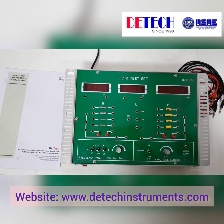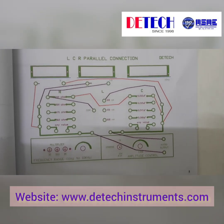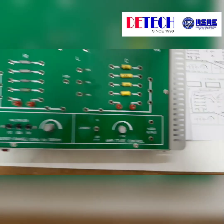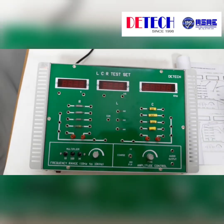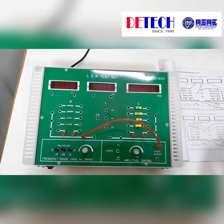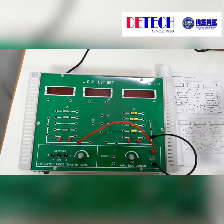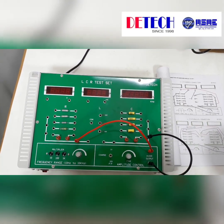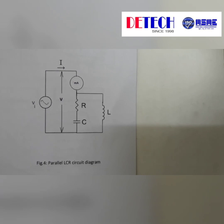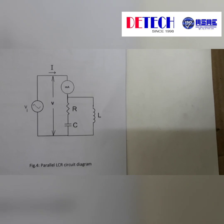Now we will make the circuit and see what we get as readings. You will find a detailed circuit diagram given in the manual. Following this circuit diagram, we'll now make the connections. We are connecting the output of the audio oscillator to the input of the onboard circuit. This is the parallel LCR circuit diagram where the audio oscillator, the milliammeter, the resistance and the capacitance are connected in series, and the L is connected in parallel.